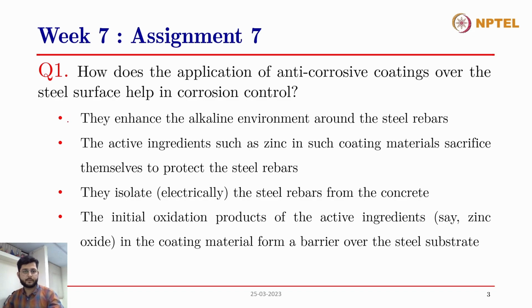All four options are correct because they enhance the alkaline environment. The ingredients such as zinc in such coating material sacrifice, yes, this is sacrificial in nature. The third one is they isolate electrically the steel rebar from the concrete. Yes, the initial oxidation products in the coating material form a barrier. All the four options appear to be correct.